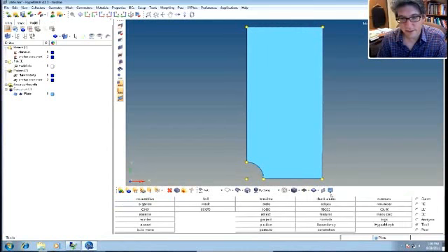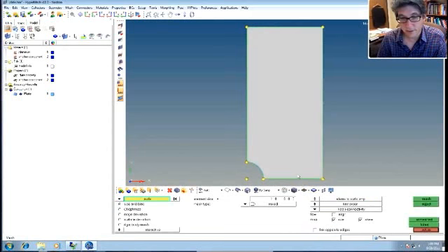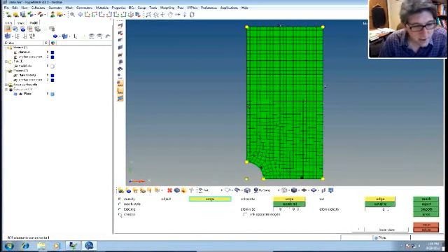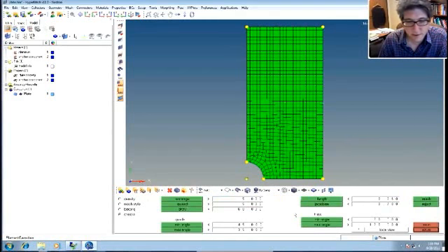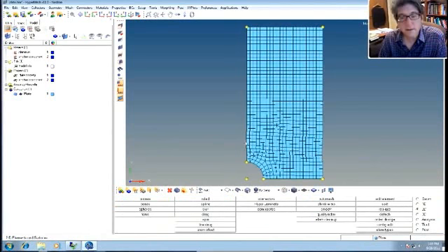Okay, so I've got the surface here. Let's go to 2D and check the surface. So we're going to do auto mesh because there already is a surface. Let's set the element size to 0.4. Okay, and then they're going to be mixed, and there we go. First order elements, and we match, and there we go. But in here, I think I can do the checks directly here, and we can check the Jacobian. And they all pass. Actually, the smallest Jacobian here is 0.78, so that's actually an excellent mesh quality. So we'll go with that, all right? So there's our mesh, okay?